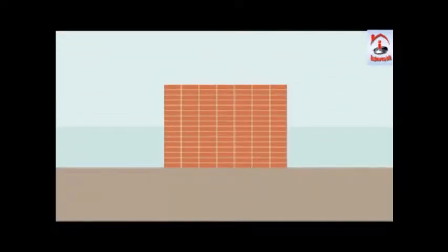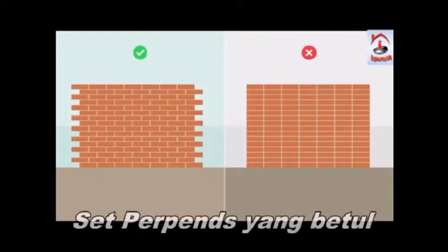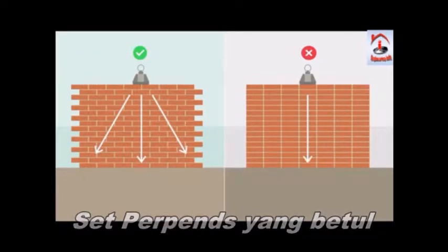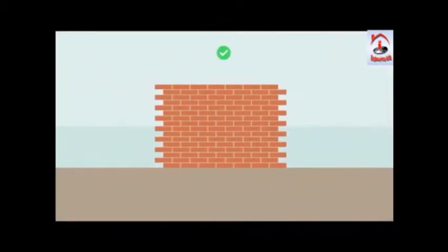An essential rule which every bond follows is to always offset the perpends of neighbouring courses. This spreads the load evenly, preventing the risk of structural failure. As a result, most walls are made of alternating courses where the bricks are centered on the perpends of adjoining courses.